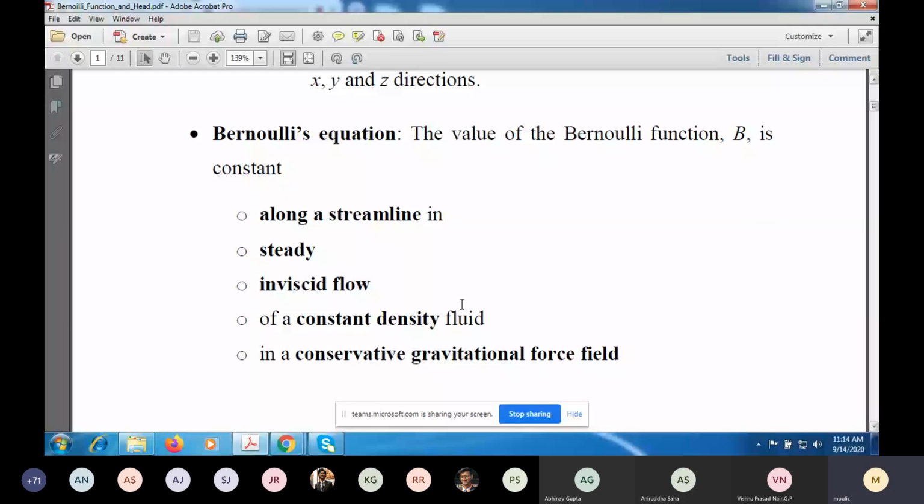So what will happen is, when you have high-speed flow past a solid plate, let us say, viscous effects are confined to a thin region close to the surface, which is called the boundary layer. Within the boundary layer, the velocity tangential to the plate will go from 0 to some value. It is 0 because the viscous fluid will stick to the surface. That is what you call the no-slip condition.